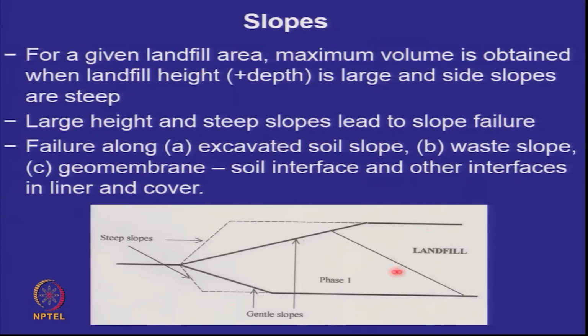And again, we are capturing this. If I give a flat slope at the top, and if I give a flat slope during the excavation, then the amount of waste that I can keep is much lower than if I can give a steep slope, both in upwards and downwards directions. So always there is an attempt to make these steeper, and we'll see how steep we can go.